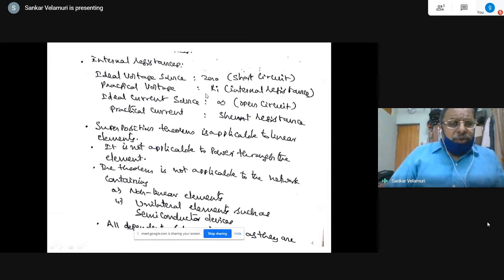That is how the voltage source and its series resistance is converted to ideal current, the current source, practical current source with shunt resistance. That itself is the source transformation. You will be understanding source transformation issue subsequently in Thevenin's and Norton's theorems also, which I am going to discuss as the second theorems today itself probably. Yeah. Now, this is with respect to DC.